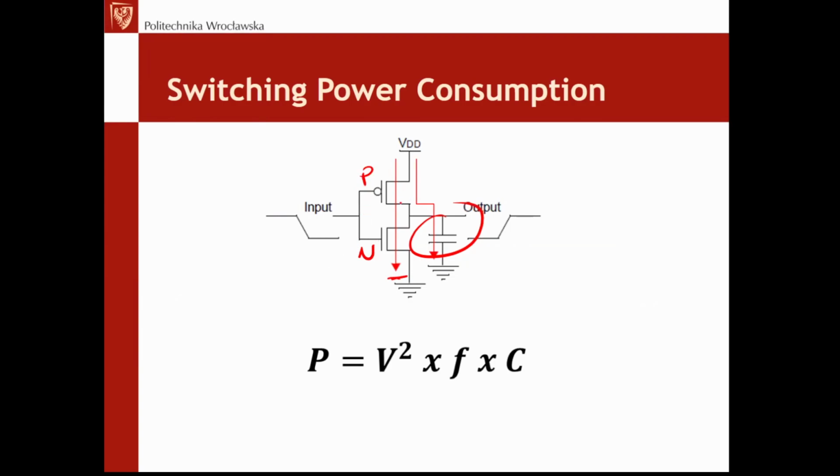Of course, only one transistor should be on at the same time, but because of, for example, the parasitic capacitance of the gate itself and the limited, non-zero impedance of the driving source, there are short moments when the current is flowing directly from VDD to ground, heating up this transistor, of course.